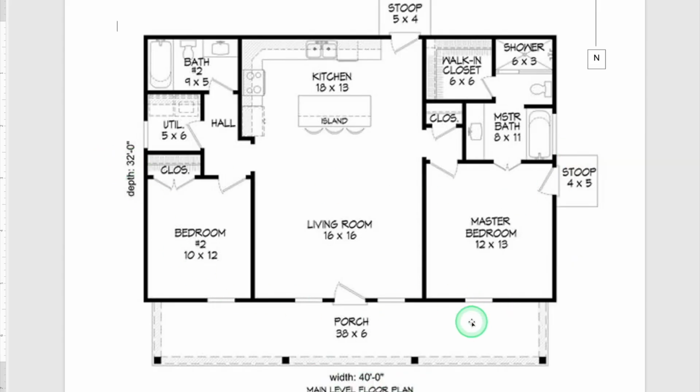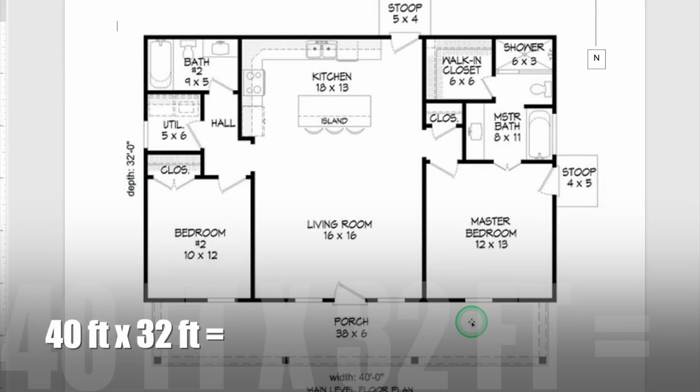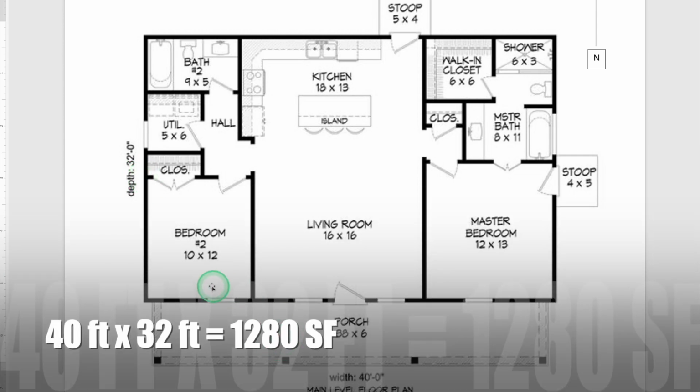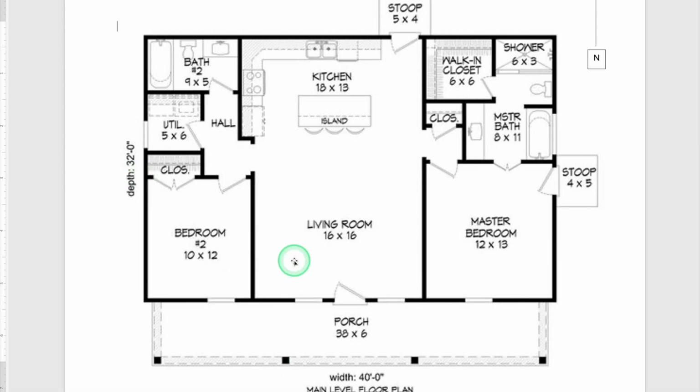So to figure out the area of the floors, you simply go, in this case, 40, because you can see the width of the home is 40 feet, times the depth of the home, so length times width, or width and depth, same thing, times 32 equals 1,280 square feet.